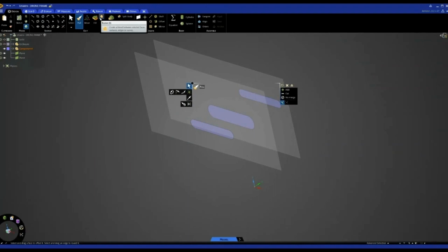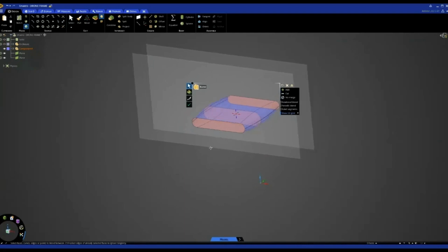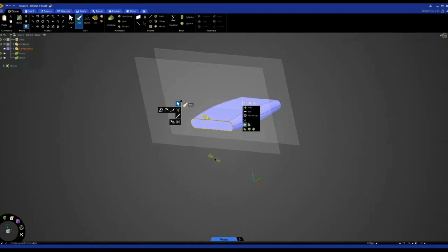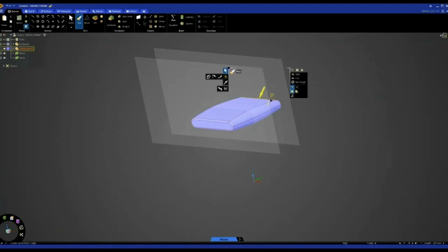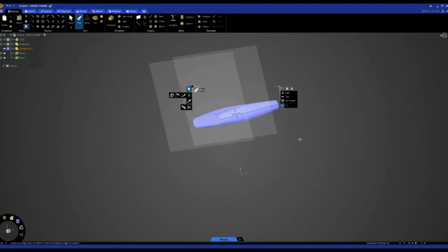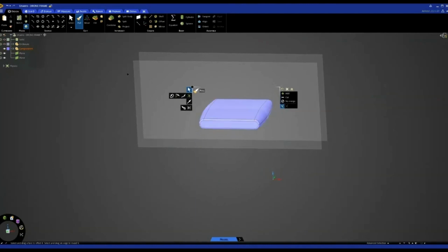I'm going to use then a blend tool, so a loft tool, just to create a profile between these. So this is my new profile. That's a little blend. Then let's finish it off by adding some rounded corners. So I can use my pull tool within here to create some rounded corners. And you can see that here. So you can see very quickly we can probably create a shape that might be more aerodynamic than previously. So that's just showing off a couple of the modeling tools.